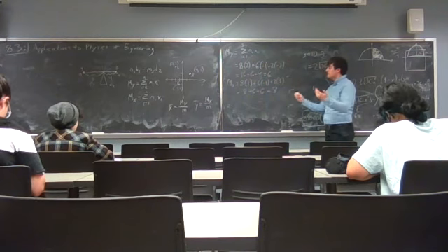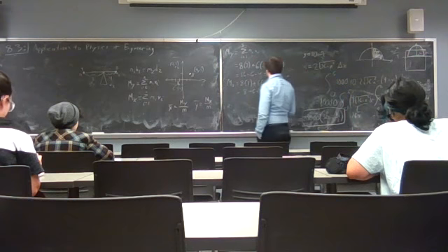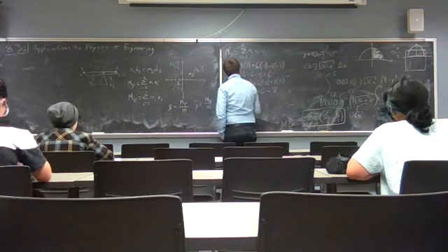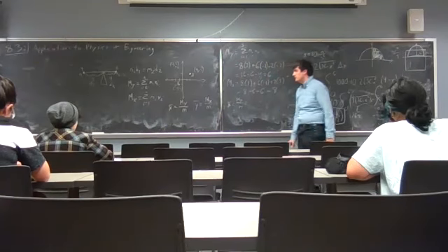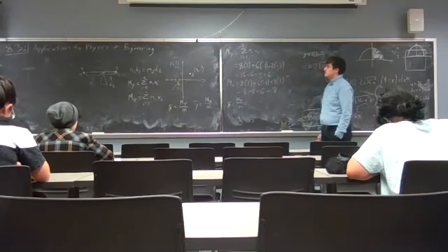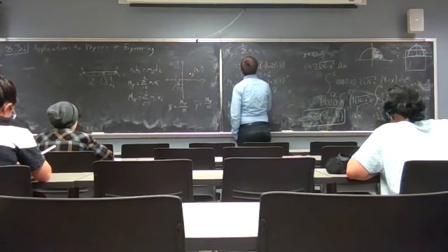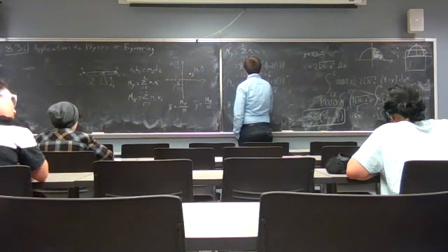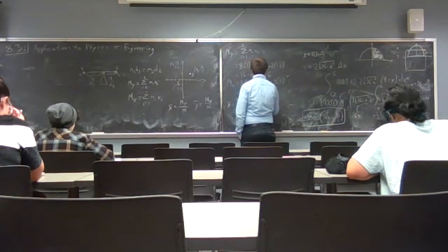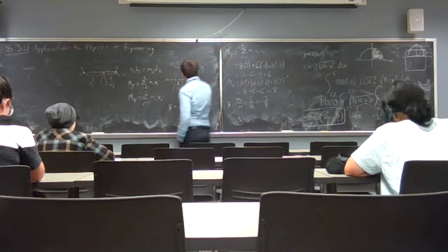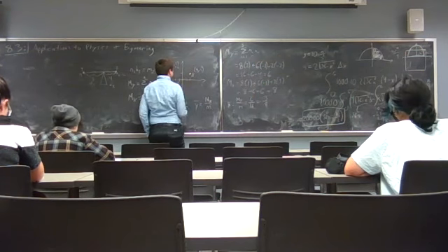Okay, now to get my points, x bar is going to be my moment divided by the total. So what is the total of the 3 numbers there? 2 plus 8 plus 6, what is that? 16. Good. So we're going to take 6 over 16, which is going to give us 3 over 8. So that is the center of my x. So that's going to be probably about here somewhere.